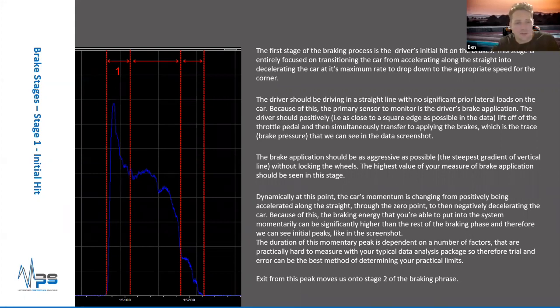That's what we're looking for when we start to analyze our data. When I've worked with a lot of amateur drivers, what we typically tend to see is this peak, the highest point. So we expect to see the highest brake pressure, highest brake applied force should always be in this first phase.